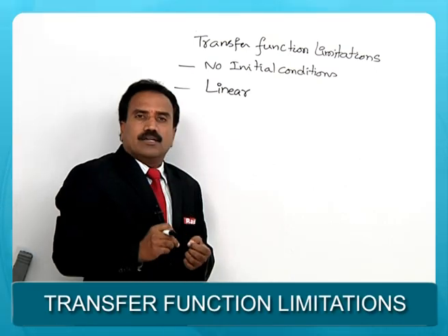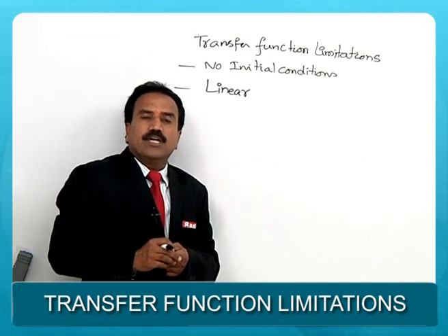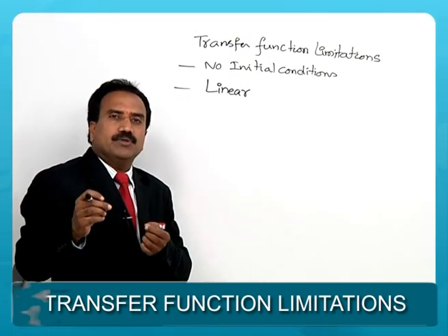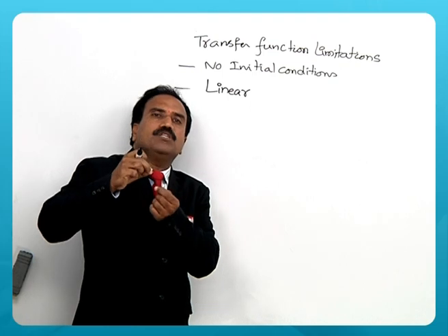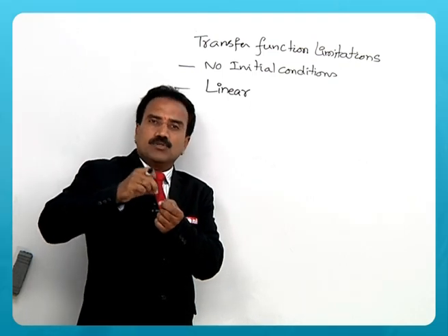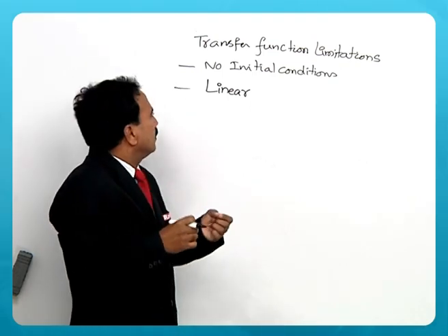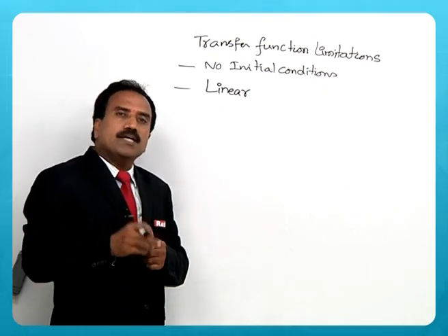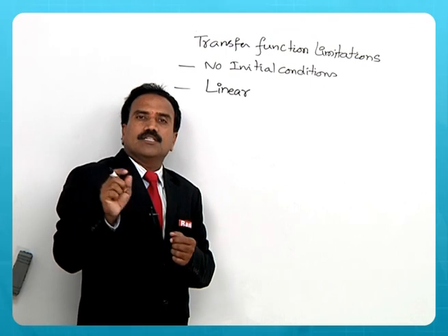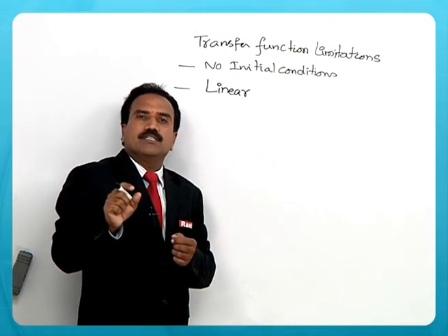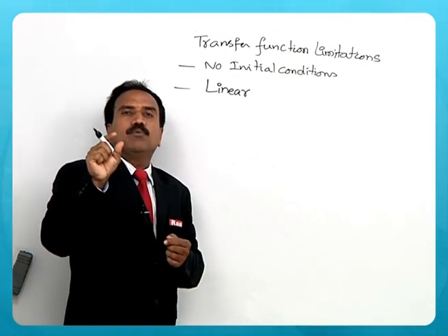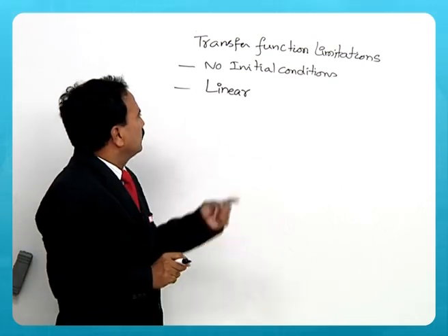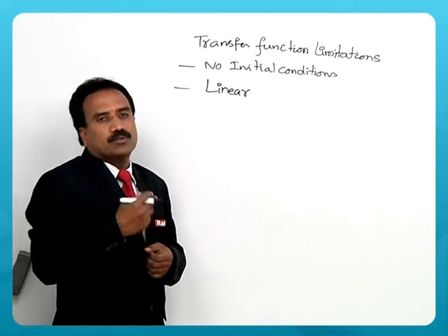So, it is justified like that. Any nonlinear system, even if you take some portion of the nonlinear graph, it looks almost linear. That means it is justified that transfer function is applied to nonlinear systems, because control of any parameter comes only for the portion of the nonlinear curve, so that it is justified though it is for linear systems.